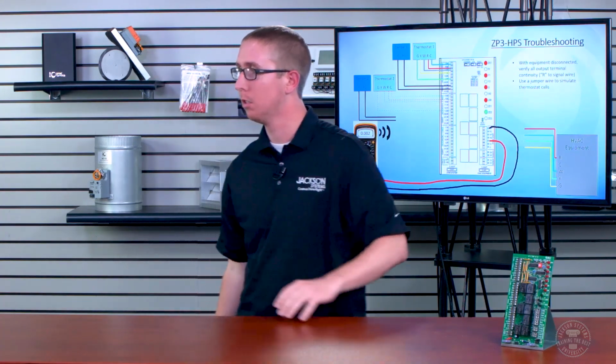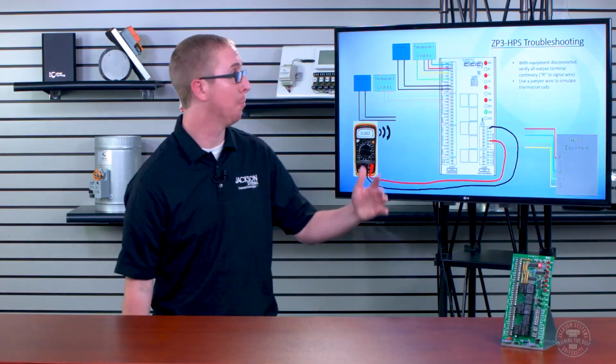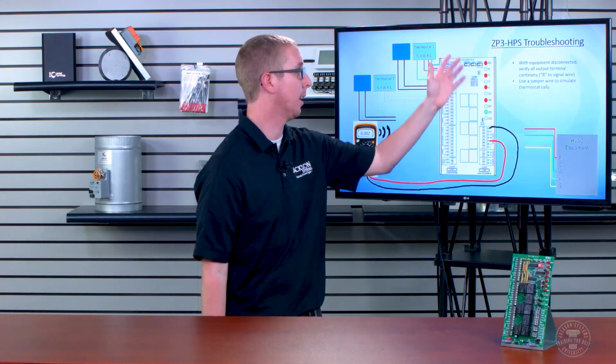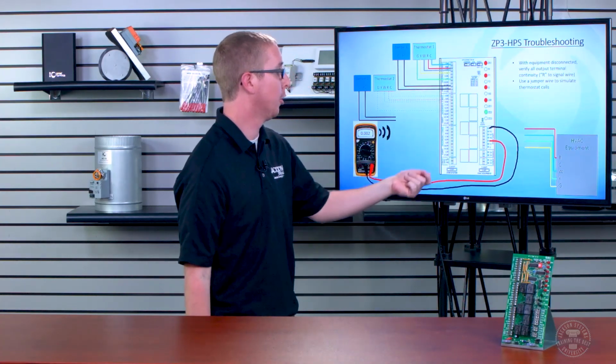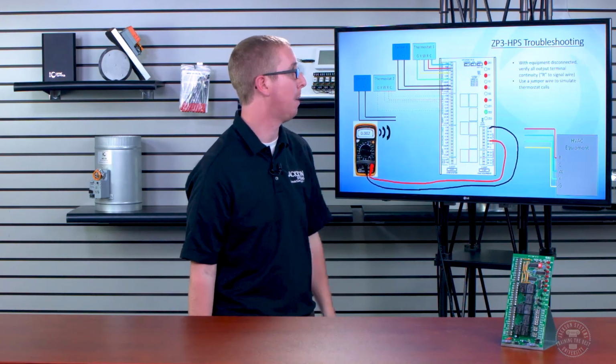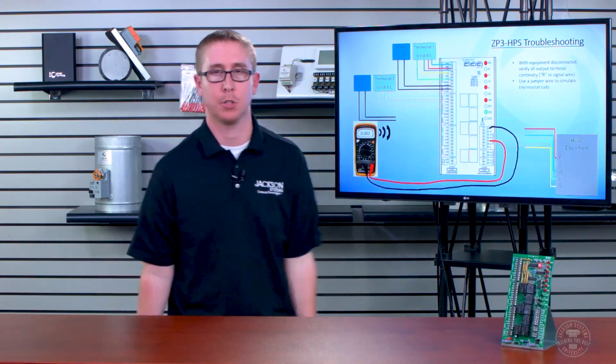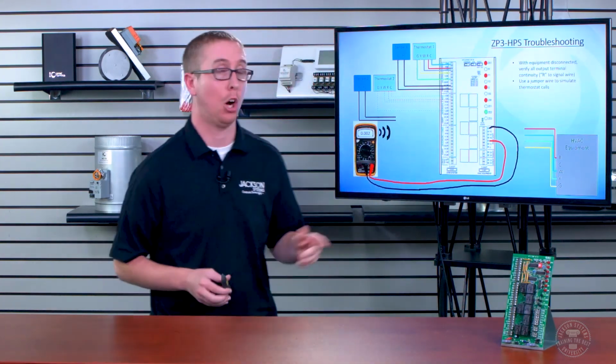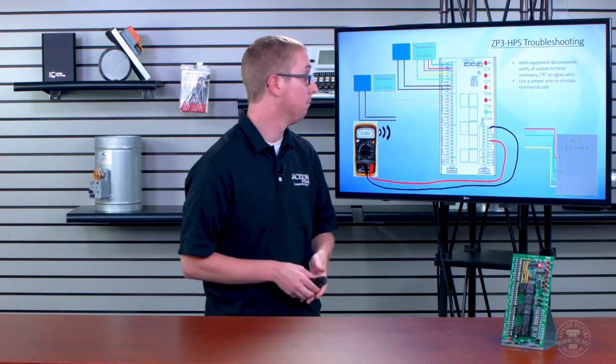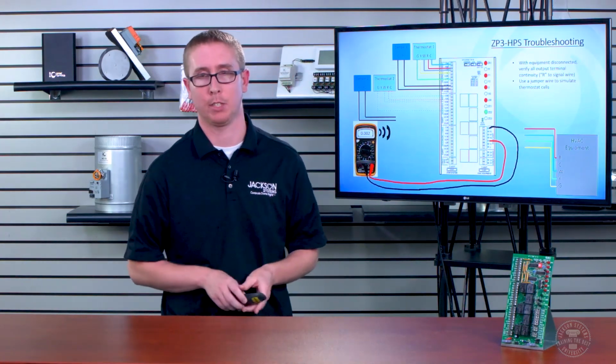Okay. Another question along that same scenario. You test continuity between R and Y with the 24-volt power on. Yes. Because simply put, without 24-volt power, these LEDs don't work. So you're only going to hear tone when its corresponding LED is on. So yes, you would leave the power on the board. You can turn off the power for the equipment transformer. It doesn't make a difference.